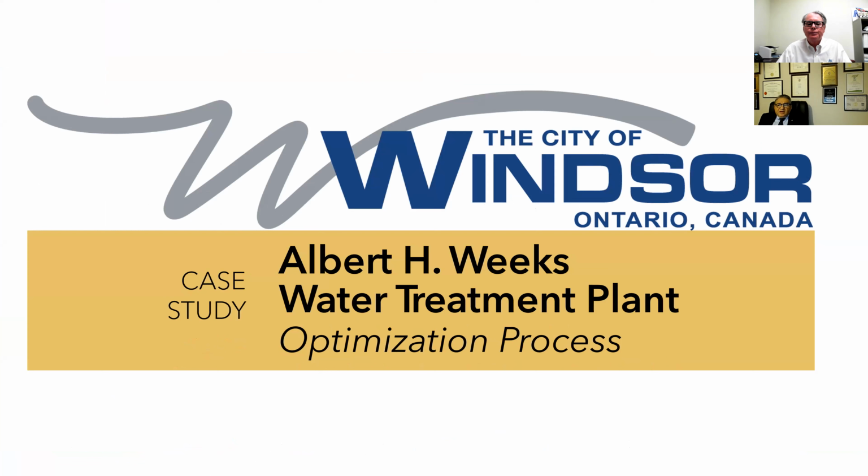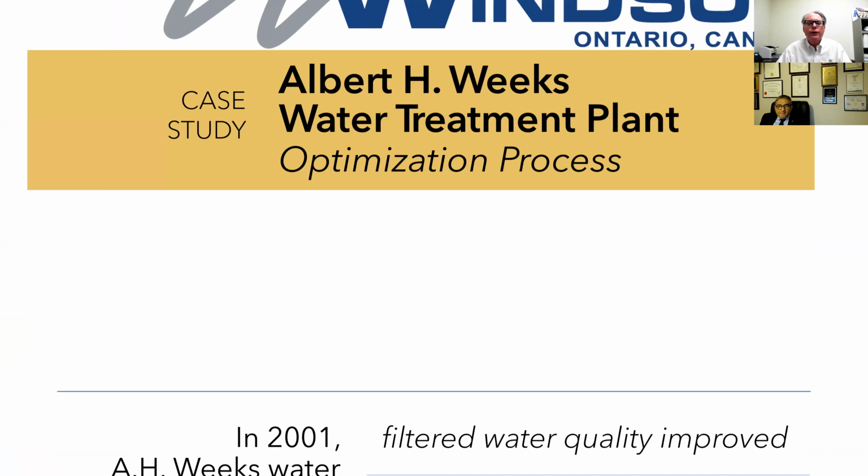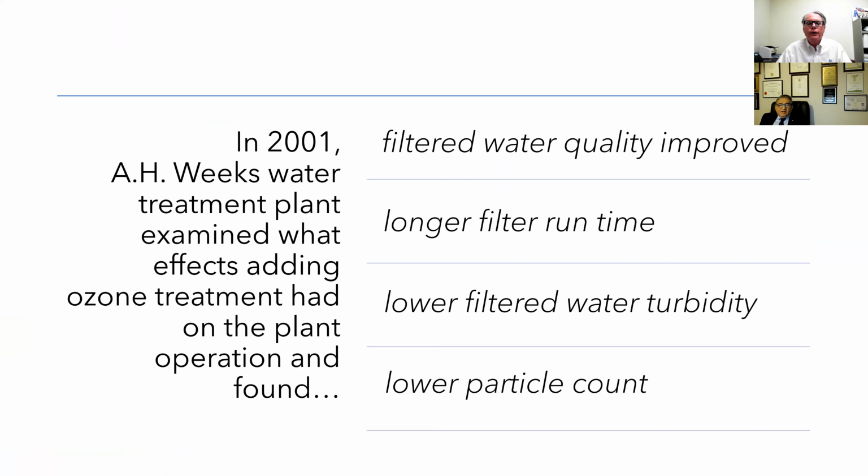The other experience we had was also on the application of ozone for the city of Windsor at the A.H. Weeks plant. This is back in 2001. The water being filtered was coming from the Detroit River, and longer filter runtime was achieved, an improvement of particle count, lower particle count, lower filter turbidity was achieved, and also a reduction of chemical use with the use of ozone.